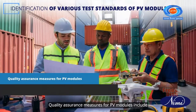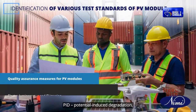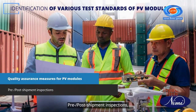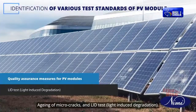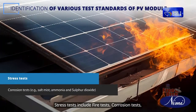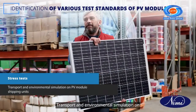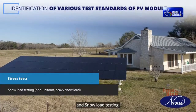Quality assurance measures for PV modules include PID, potential induced degradation, electroluminescence and IR imaging, pre or post shipment inspections, aging of micro cracks, and LID test, light induced degradation. Stress tests include fire tests, corrosion tests, outdoor long-term tests in different climate zones, transport and environmental simulation on PV module shipping units, sand abrasion tests, and snow load testing.